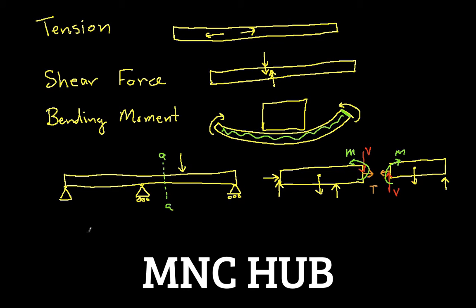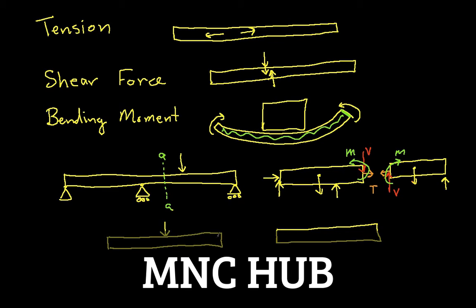When you talk about internal forces, you need to be a little careful. When we've talked in the past about free body diagrams and we're assuming that we have completely rigid objects, we've talked about the idea that maybe gravity can be represented as just a force at the center of gravity of the object. But when you're looking for internal forces, you have to make very clear whether you have a concentrated force. So a concentrated force you might think of as an elephant wearing an ice skate standing on this beam. So the force, the weight of the elephant is applied at pretty much exactly one point, versus a distributed force.